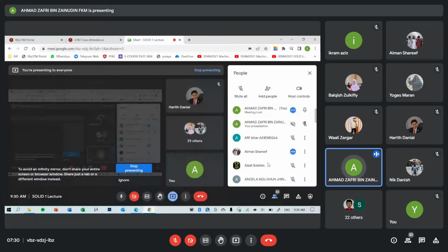Right now, FB is under axial load, so we can use the P over A formula to calculate the stress in this member here. But the cross section is not the same. The cross section for FH is smaller as compared to the cross section for HB, right? So which section do you think the stress is higher? FH or HB? Which part of this member is the stress higher?